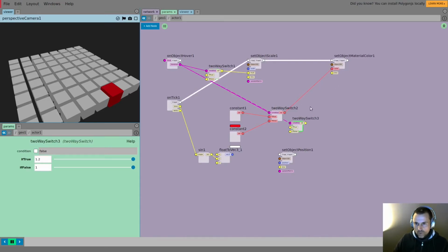So I'm going to copy this one, and let's say I want to have a lerp of 0.2 when I'm moving the mouse over the object, but a very small one, 0.01, when I am moving away from the object. So that's what happens. You can see now that we go to red quickly, but then we go back to white more slowly.